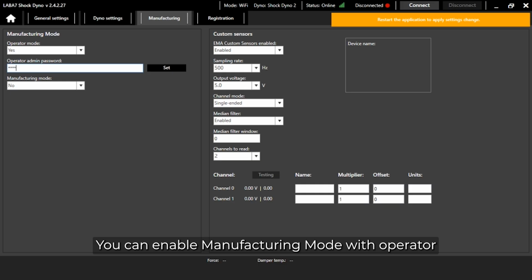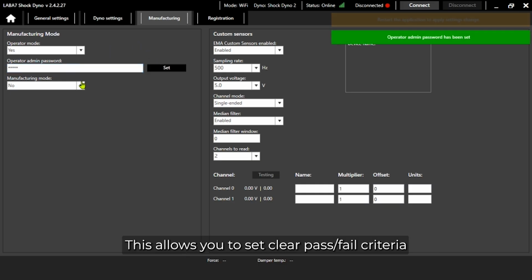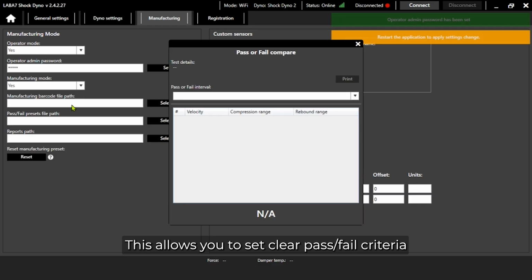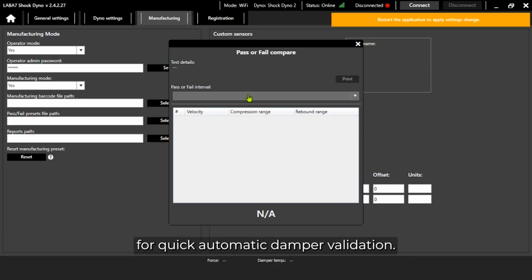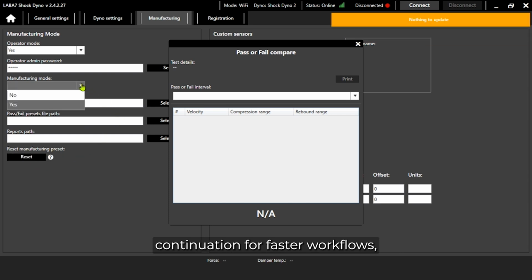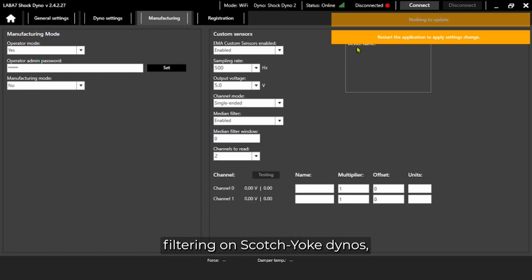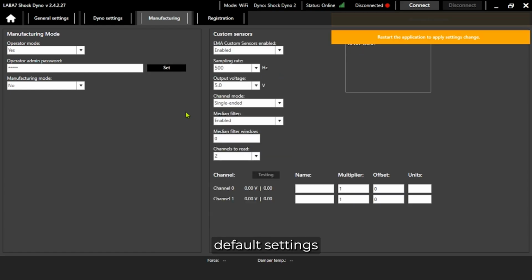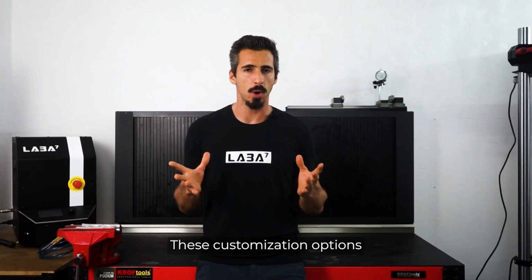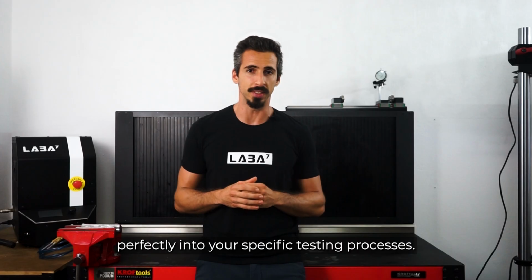For manufacturers or high-volume testing environments, the manufacturing mode license provides powerful features. You can enable manufacturing mode with operator passwords for secure access. This allows you to set clear pass-fail criteria and integrate barcode schemes for quick automatic damper validation. You can also automate test summaries, enable automatic test continuation for faster workflows, adjust load cell filtering on Scotch-Yoke Dynos, and define default settings for preload and first-run average force elimination. These customization options help ensure the software fits perfectly into your specific testing processes.